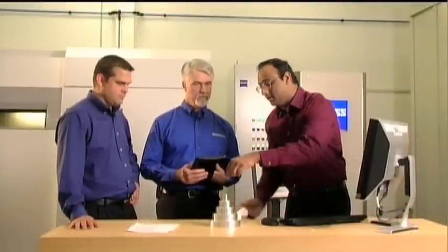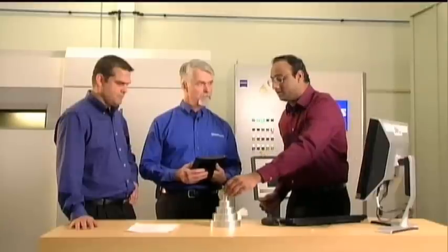So now, for a smaller sized edge, I get a very good signal because the X-rays go from one end to the other really fast. But I have more material at the bottom. In this case, now I get a weaker signal because they have to travel a longer path. But in case of this part, the step cylinder is a very good example because this internal bore diameter doesn't change from top to bottom. So even though the intensity of X-rays that are being collected at the top and bottom are different, our ability to go in and find the true edge is what creates the more accurate file.